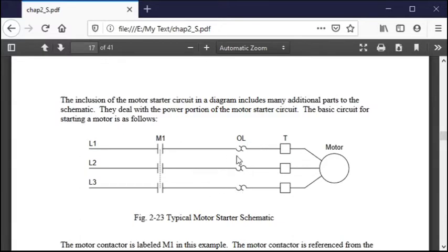These are sensors. They're devices that are set for a certain current, and if they go above that current, they heat up a device that will trip a switch that turns the motor off. So in other words, these are not the switch, but they interact with a switch that will allow the switch to turn off the motor. So this is a sensor. You have a sensor in each of the legs, and those are called your overloads. Then there's an overload switch, which we'll talk about in a little bit.